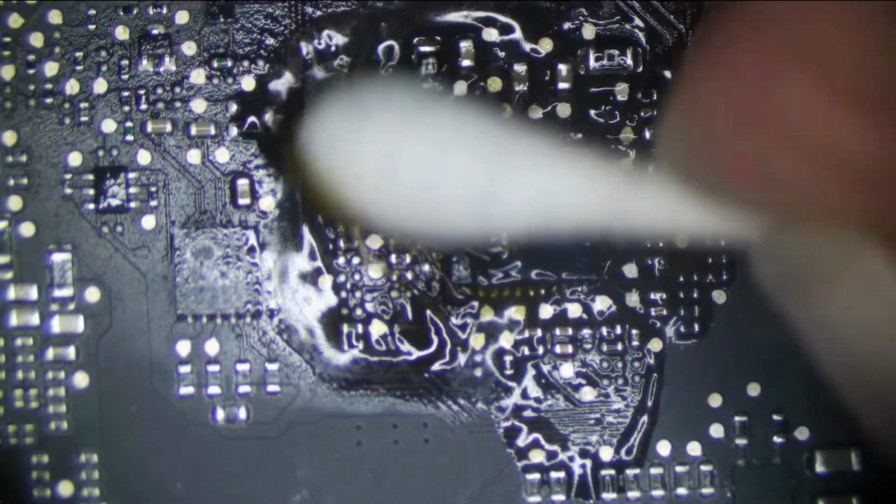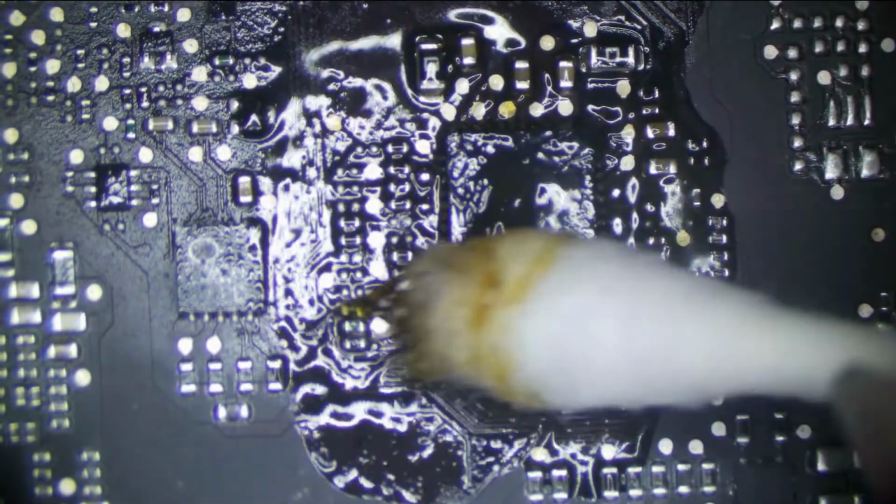Now, I'm going to put this in the enclosure, so most of the time this is going to fix it. However, we have coffee under a VRAM chip, so it's probably not going to be happy. So what I'm going to do is actually reflow that before, just in case. I don't want to cause any more damage to it. Now, you may hear me talking about reflowing. This is a completely different case.